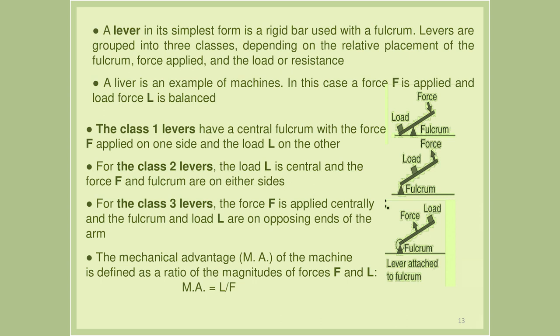A lever is any rigid segment that rotates around a fulcrum. A fulcrum is a point of support or axis about which a lever rotates. A lever system exists whenever two forces are applied in a way that they produce opposing moments. Based on the arrangement of load, effort, and fulcrum, levers can be classified into first to third class.